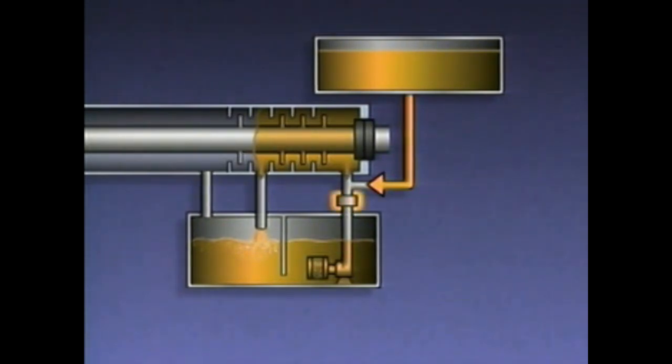The check valve keeps the oil from the head tank from flowing down into the oil pump and forces it to flow through the seal. The head tank contains enough oil to allow the compressor to be shut down without a gas leak if the seal oil pump fails. The next components we'll look at are bearings.